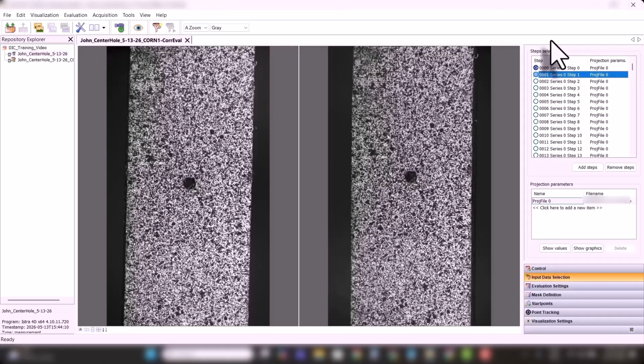In such cases, it's generally best to simply remove the undesirable starting images to where the first remaining clear image, which after removing images will be relabeled as step 0, will become the reference image. So if images are added or removed and you don't see a reference step defined by this marker, then just right-click on the step and select that step as the reference step, and the marker will appear.